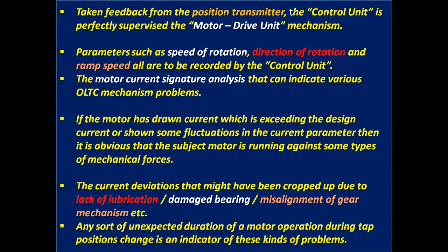The current deviations might have cropped up due to lack of lubrication, damaged bearings, misalignment of the gear mechanism, etc. Any unexpected duration of motor operation during a tap position change is an indicator of these kinds of problems.